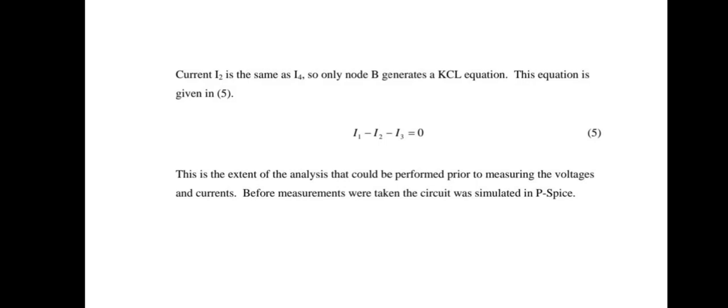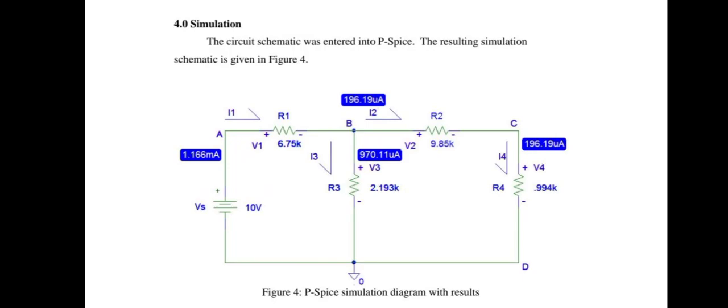The voltage and current values were measured and placed into the KVL and KCL equations to determine whether they turned out to be as predicted. These measured values were then used in the Ohm's law equation to find resistance. The calculated and measured values were then compared to the expected results from the theory in section 2.0. All the differences between tested and expected values were small, therefore all three laws could be considered valid.